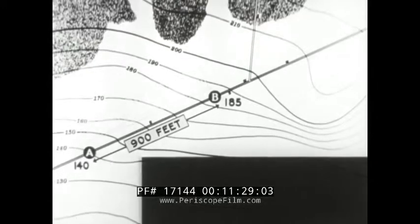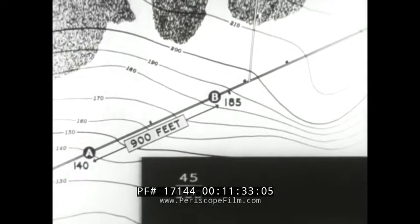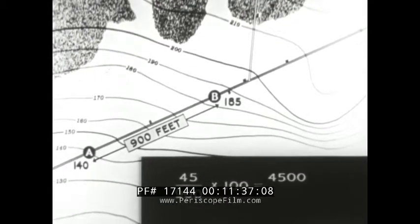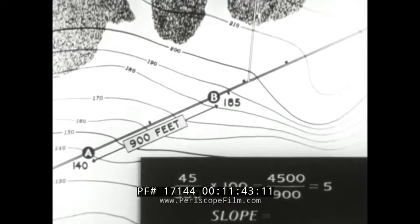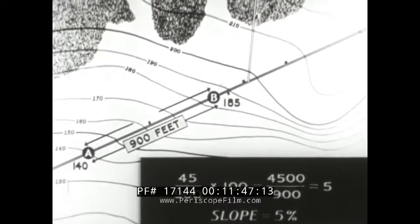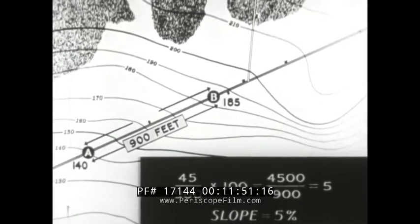To obtain the percent slope, divide the difference in elevation, 45, by the horizontal distance, 900, and multiply by 100. 4,500 divided by 900 is 5. The slope is therefore a 5% slope. Since the points A and B are on the road, this portion of the road is said to have a 5% grade.